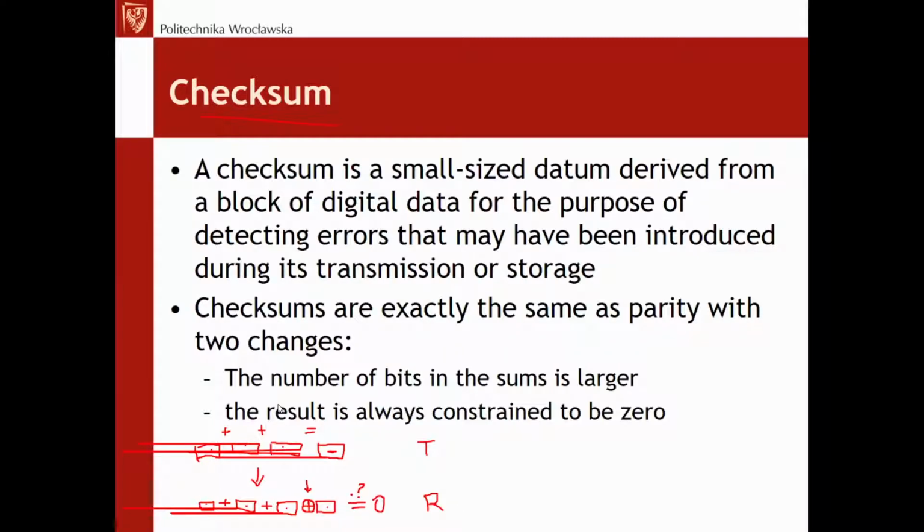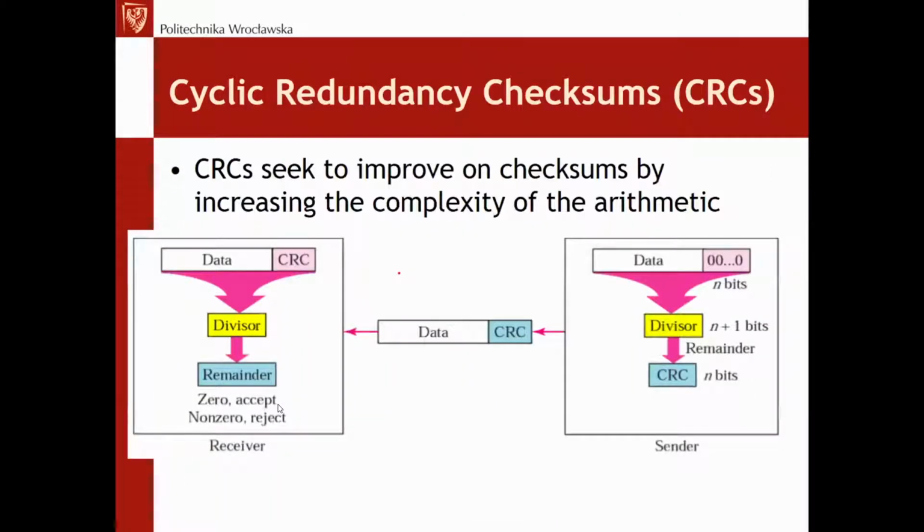The decoding is as well simple. So the checksum, from the microcontroller's point of view, from the application's point of view, and from my experience, proved to be a very, very valuable mechanism. It's not as good as the next one, the CRC, frankly, but still it's very simple. And for small microcontrollers, the checksum is definitely better than the parity.